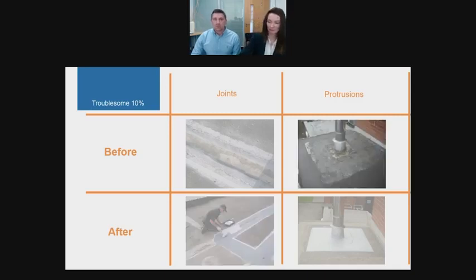For protrusions, anything that penetrates through the roof needs sealing. In this case, a pitch pan or exhaust vent. Almost all sealers used will eventually crack due to loss of plasticizer or aging. If it is not stabilized or repaired, the vibration or movement of the penetration can cause the sealant to crack.